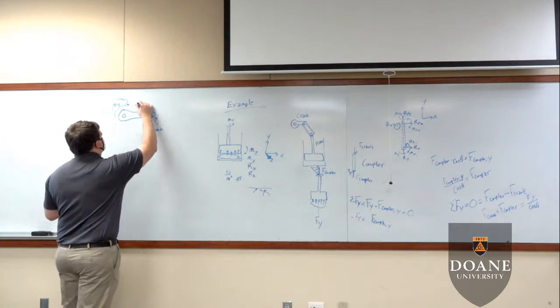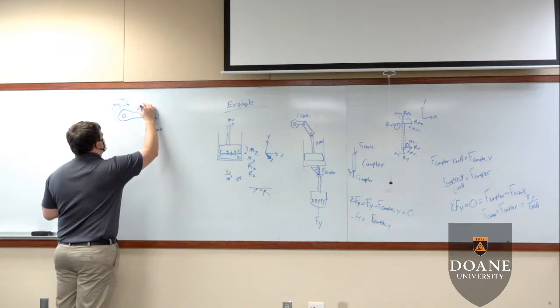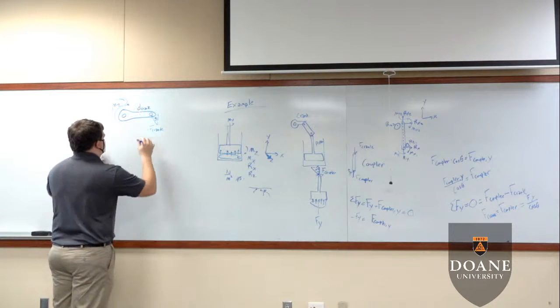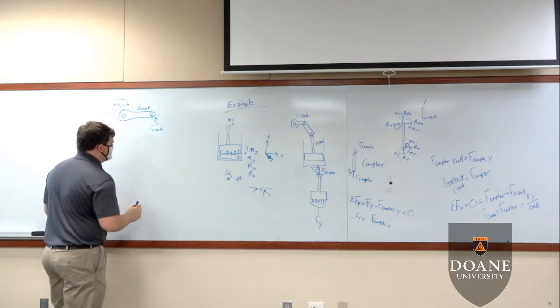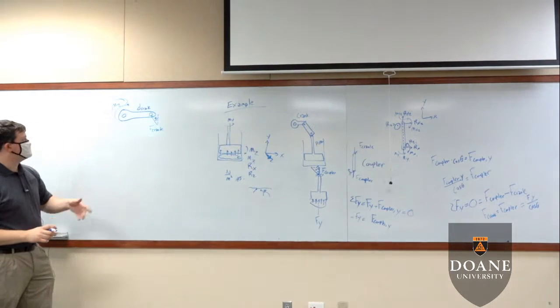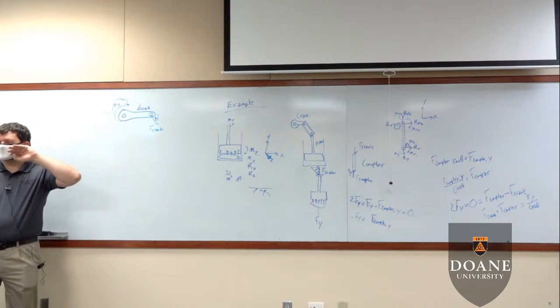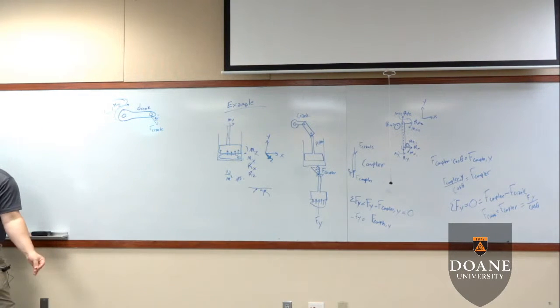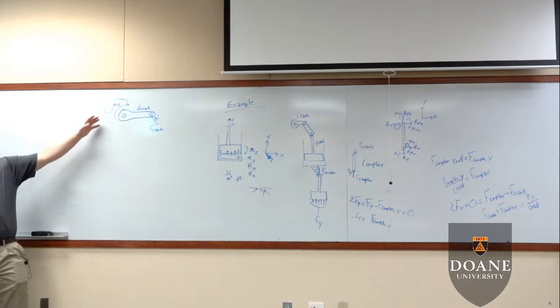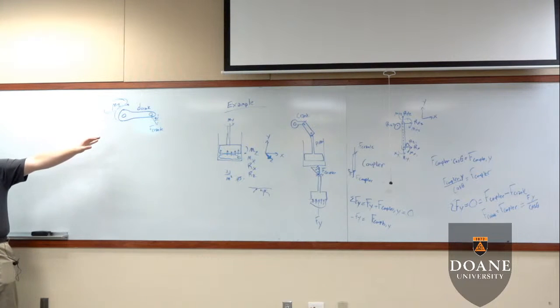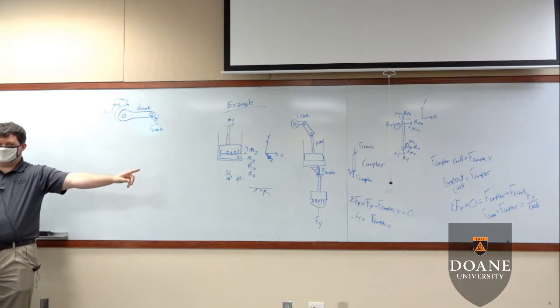Okay, we know what the crank distance is. I'm going to go ahead and call this D crank. That's the distance between the two revolute joints. I'm going to figure out what MZ is. Now, MZ is, in fact, a revolute joint, but it is rigidly welded to an axle whereby the torque can be carried through the axle.